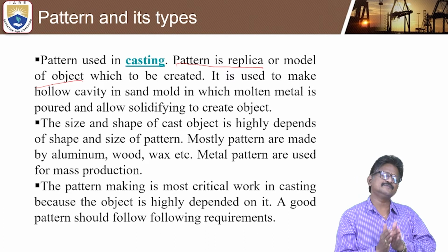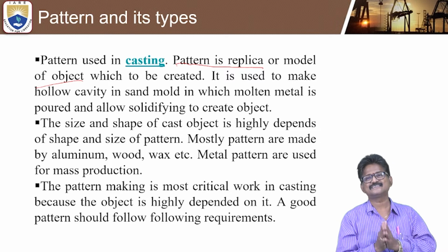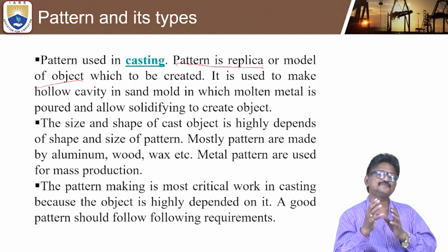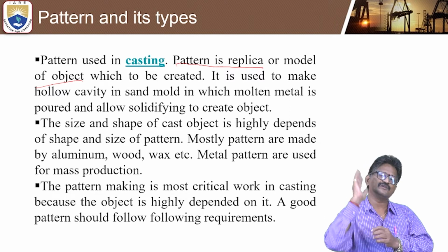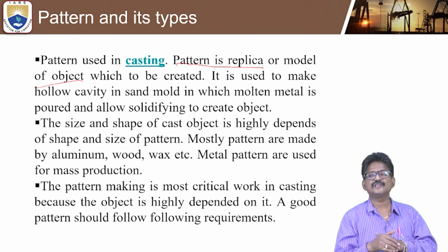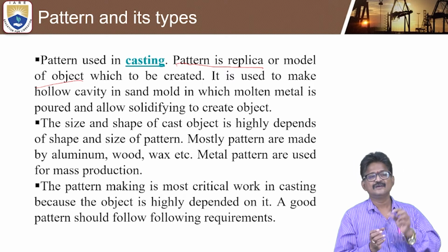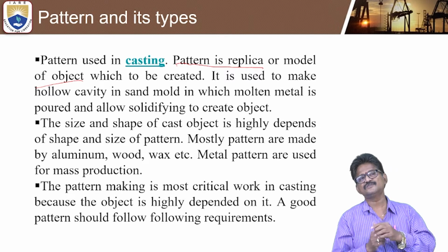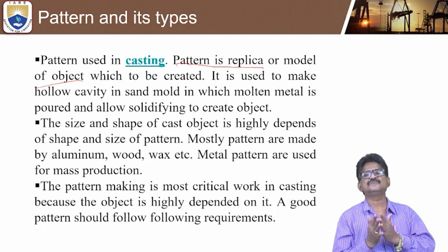Yes or no? And similarly, if you want to use a metal pattern, if you prepare the pattern in metal, it can be used for lakhs and lakhs of components, and the life of the pattern will also be longer. That is why, with a metal pattern, the quality is also good, a larger number of components can be produced, and the component shapes can be easily made.